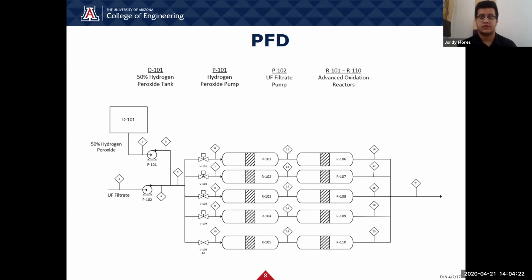We decided to use smaller reactors in a parallel system, which will help us have less scale-up variability. The top 4 pairs will run 24/7, while the ones on the bottom will be used just in case any reactor needs maintenance, so we don't have to stop the system at any point.